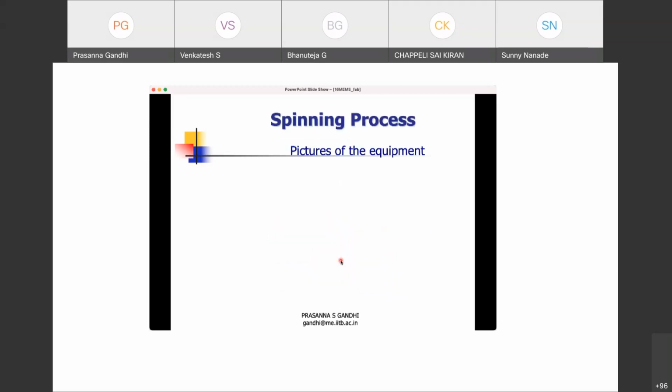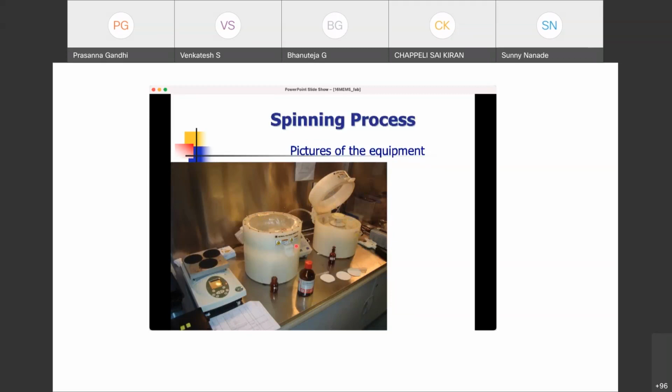Okay, so you can see some of the pictures of this equipment here. Now this is a spin coater actually. You have this cover for the top, and then there is a stage with this black O-ring that you are seeing there. You put a wafer on the top of this surface and you create a little vacuum there. So between this O-ring and the wafer, you create a vacuum, so the wafer gets held by vacuum to the substrate. There is no other way to hold the wafer, typically, in these MEMS processes.